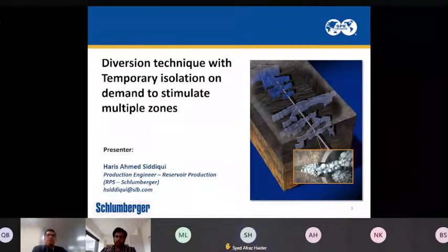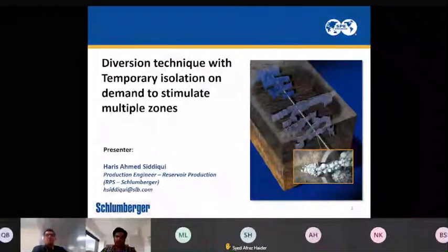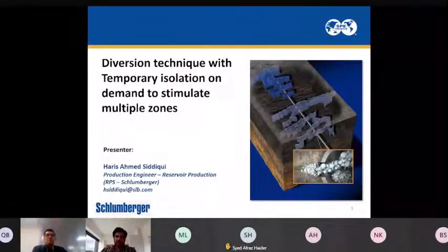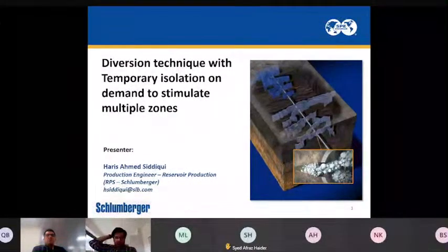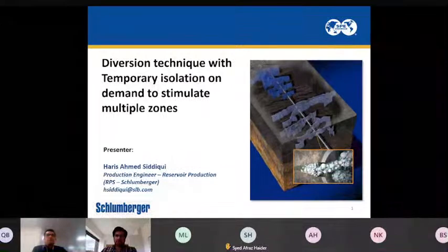For coil, I don't think we can pump it because this is a very thick material, and even in a vertical well there is a high risk. We had taken that risk and we have successfully implemented it. But even with 3.5-inch tubing, there are still issues pumping this because it's a very thick slurry. Again, we need to design or engineer it in a way that we can. But coil tubing, I don't think will be feasible to pump this material.